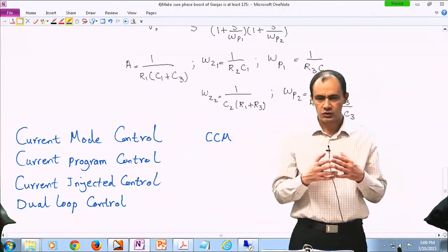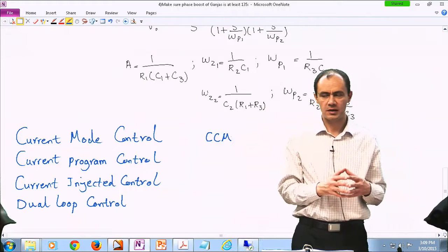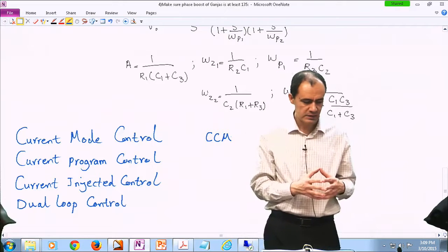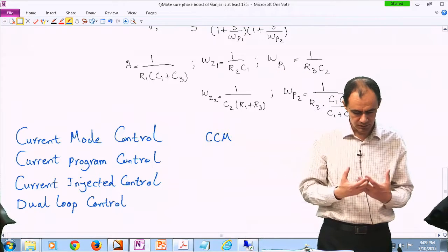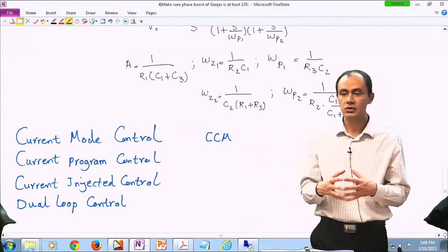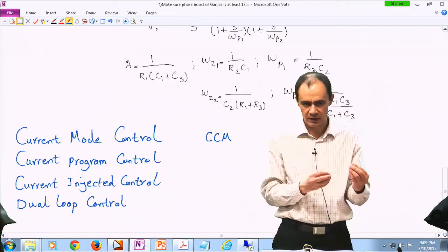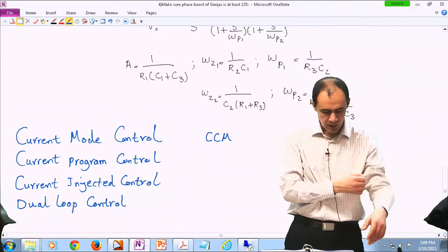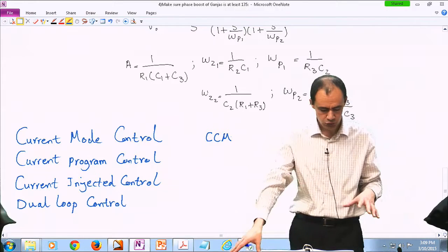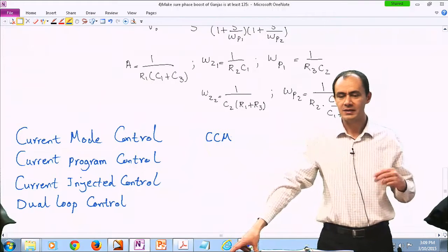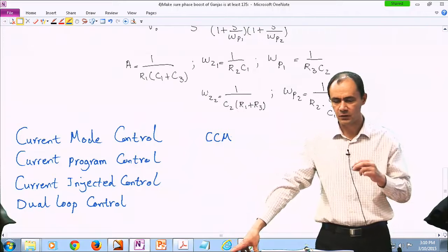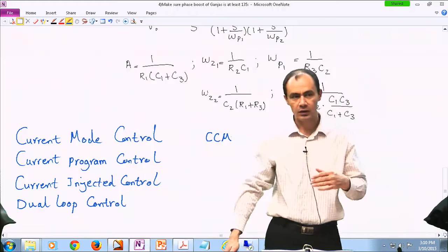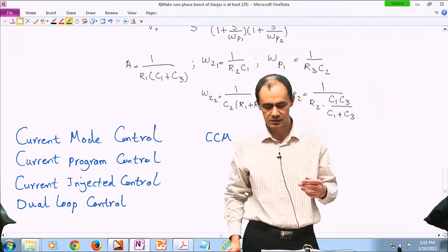So the whole idea is we have a power electronic converter. Even in the simplest converters possible, there is at least one capacitor and one inductor. Each capacitor and inductor, by their very basic feature, are energy storage devices. So they have some memory. They are actually like integrators, basically. And from a control perspective, they represent a state in the system. So the voltage of a cap is one of the states in the system, if you go back to a state space representation. And the current of an inductor is one of the states in the system.